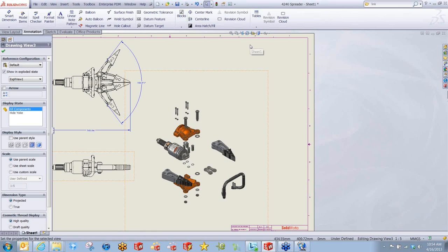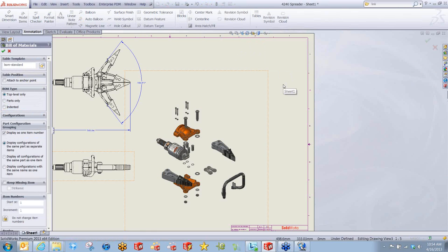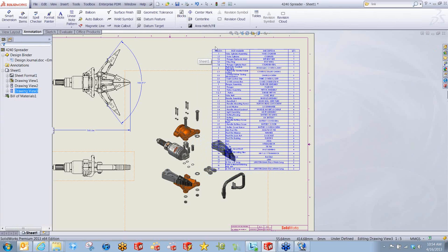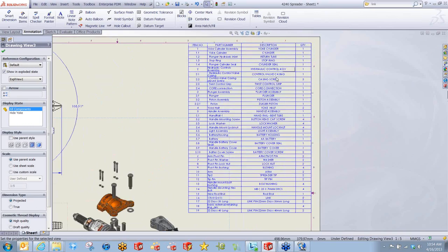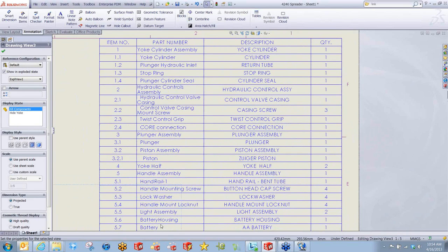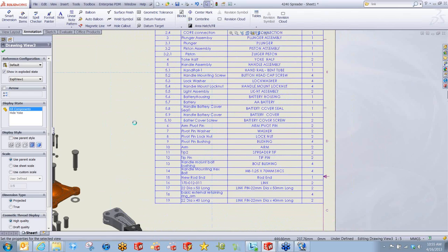And now for the really important part of our assembly drawing, that bill of materials. Keeping track of part quantities, costs, things like that. I want a nice indented BOM, with some good numbering here. We'll hit OK. And you see I get quite a big BOM list here of parts. And keeping track of all the quantities for me, all that metadata from the data card and from the title blocks of those parts populates right into the drawing. And again, we could have part numbers in here as well.